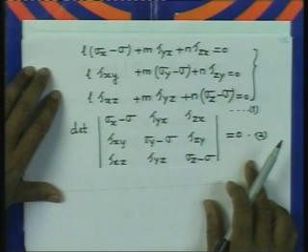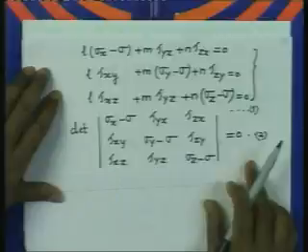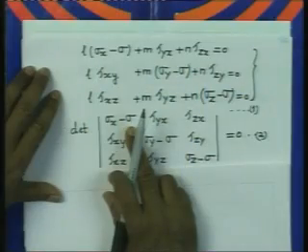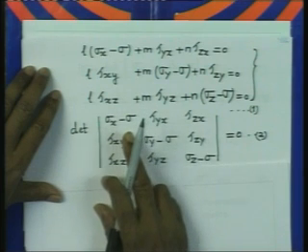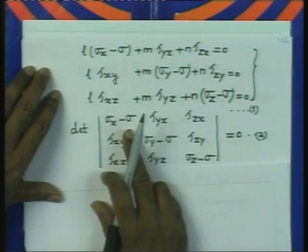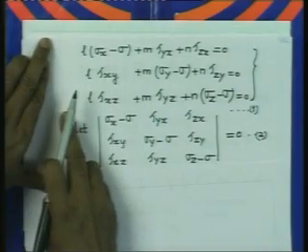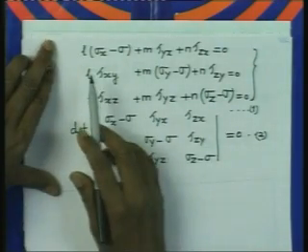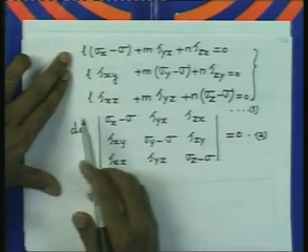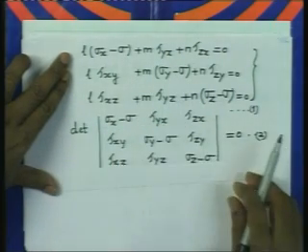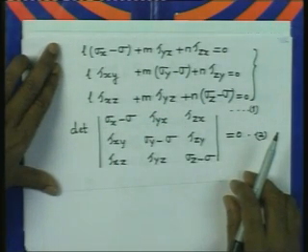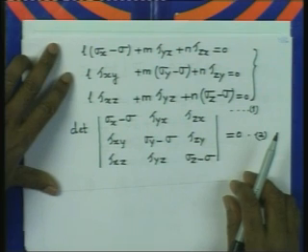Now, the question is, how do you get the direction cosines corresponding to a particular value of sigma? You take the value of sigma, let us say sigma 1, substitute in these 3 equations, thereby you will get again 3 equations involving L, M and N. Solving these equations, you are going to get the direction cosines corresponding to the stress sigma.